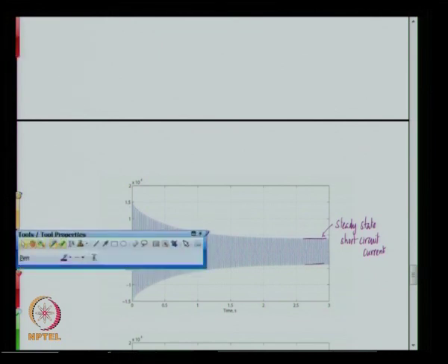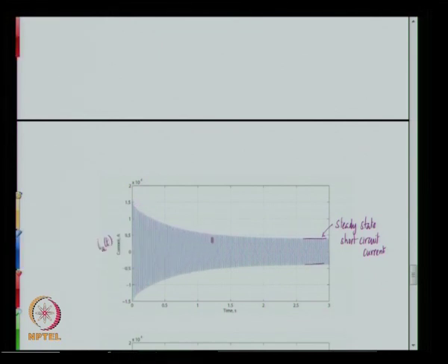This region is the exponentially decaying part. The envelope, as you can see, seems to show a nice exponential decay, and in this case the short has been done assuming that lambda equal to 90 degrees, and therefore there is no DC component that can be seen. If lambda were something else, then there would be an exponentially decaying DC component, either decaying from this side or from this side, and then the entire waveform will be bent over from one side, finally reaching the steady state values.